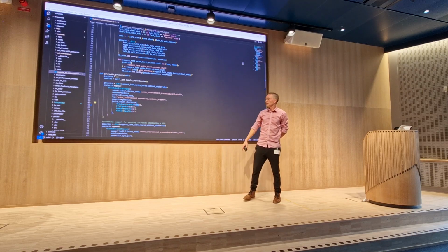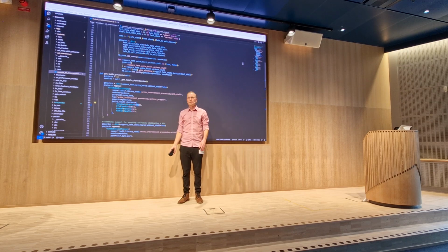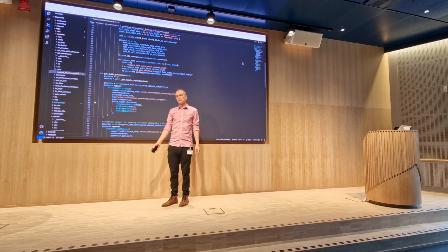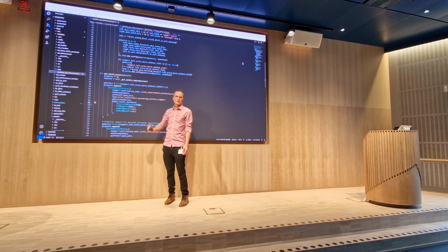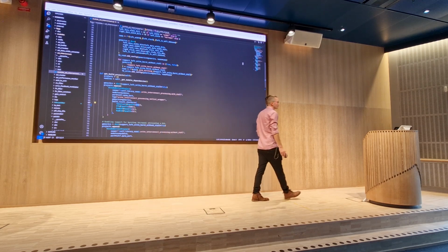And then you can select here which kind of resources you're interested in, like if you make a multiply accumulate implementation, you want to make sure that it uses 1 DSP, not like 10 DSP, right? And if you want to be a bit more relaxed, you can tell it to use less than 400 LUTs instead of exactly equal to.